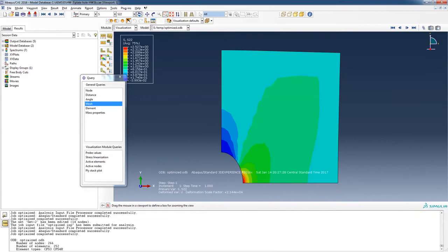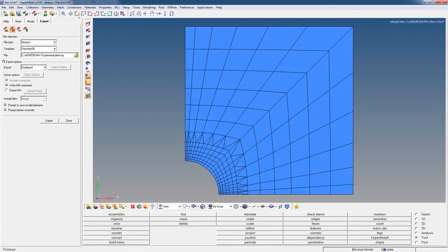Now, if you're really good and experienced with building finite element meshes, you could start off with an optimized mesh that looks pretty much like this and get pretty close to what we would expect to be the right answer for our particular stress analysis. Now, I will say, particularly for academic use, I am very picky when I'm on a student's committee and they do finite element analysis and they haven't done a convergence analysis. We really need to know how good is our answer. And from this point on in the course, whenever we do a finite element mesh, we need to keep in mind that we should do a convergence analysis to see if our answers change with the mesh. If the answers stop changing with the mesh, then we have a converged result.